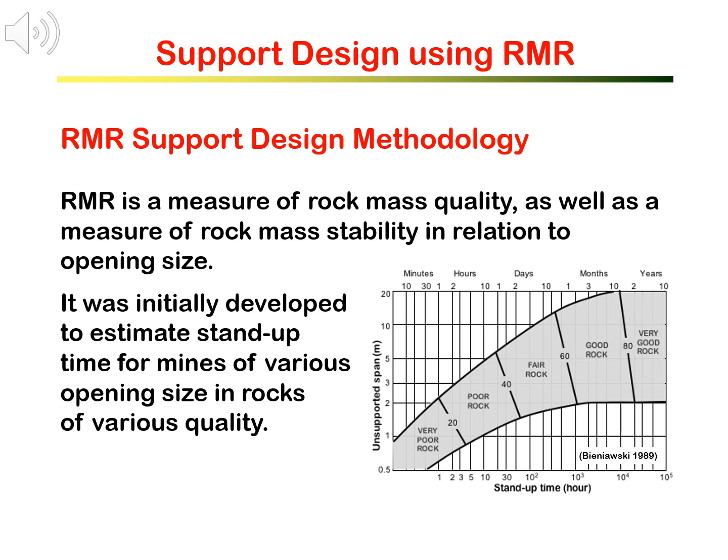one of the advantages of using RMR is that it has been coupled with unsupported span and stand-up time, as shown by the chart on the right.